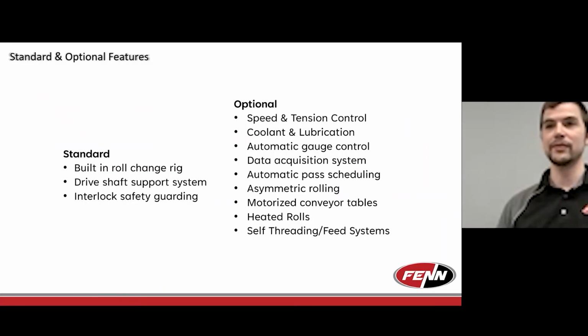That's very commonly used when there's concerns, based on the amount of work being done and the production being run, with the rolls heating up and thermally expanding, or there's worry with the material heating up and starting to metallurgically break down. That's where coolant is very frequently used. And then lubrication is frequently used as well when, based on the way the material behaves, you need to have some type of lubricant to prevent it from sticking to the rolls, or you're worried about what the roll is going to do to it under reduction from a metallurgical standpoint, and using lubrication can assist.